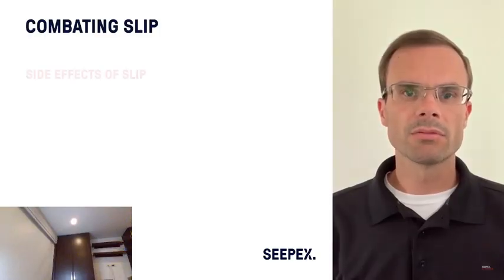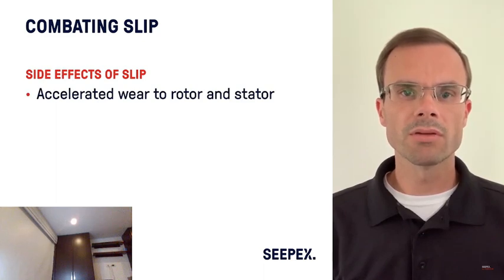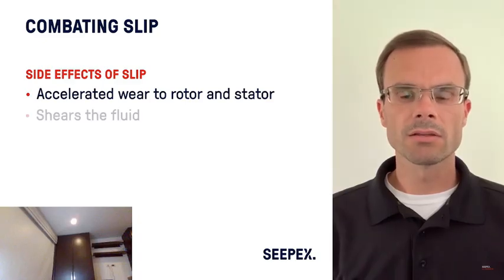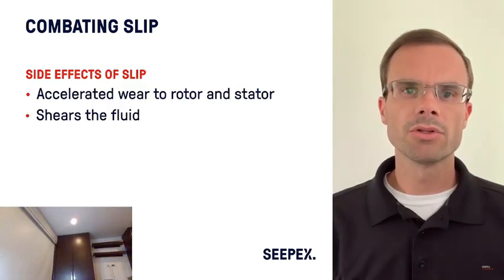Slip can be detrimental for a couple of reasons. First, slip can cause accelerated wear to the rotor and stator for abrasive fluids. Second, slip actually shears the fluid, which could cause damage to the product. So how do we reduce, eliminate, or compensate for slip?